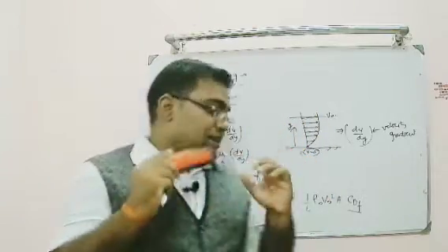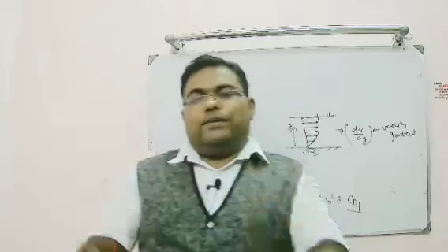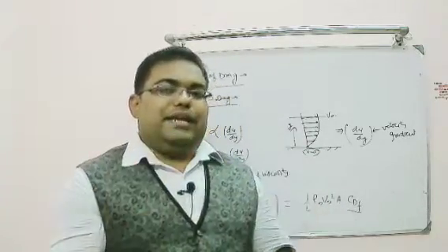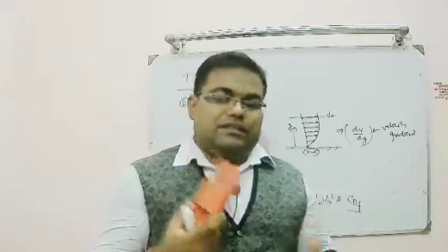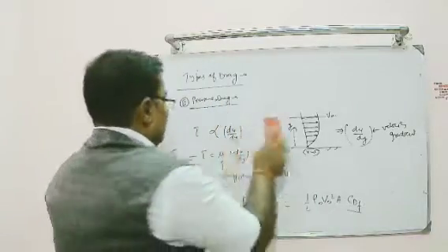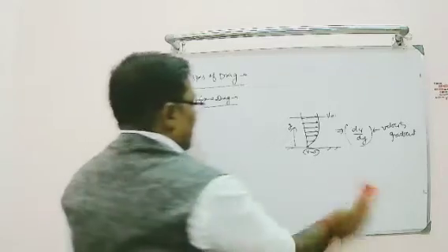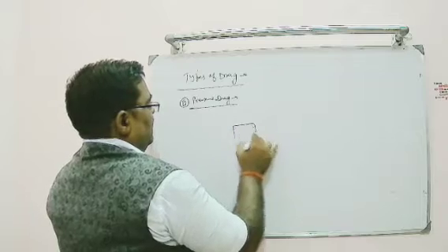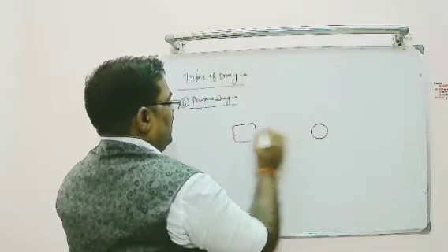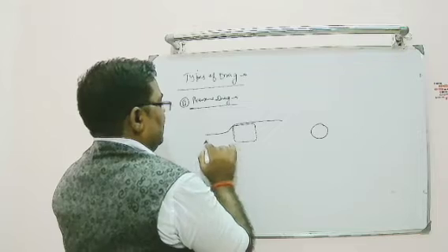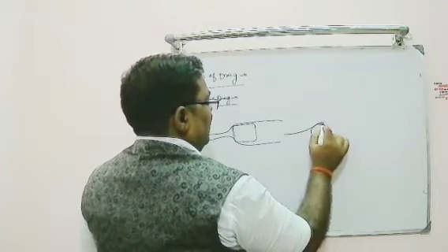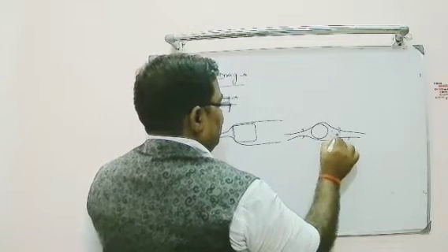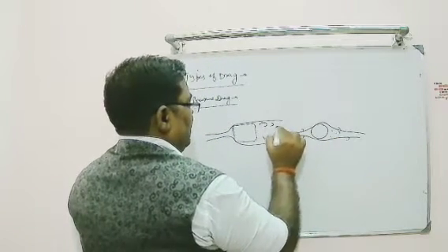So basically the pressure drag depends entirely on the geometry of the object, and it can be minimized by making your geometry more streamlined. That is known as pressure drag. So things are very simple. It's due to geometry. This is also known as profile drag. So if I am considering this case 1 and this case 1, in this case the flow will separate like this. In this case the flow will at least travel and then separate. So we will have this much range of what we call the wake region.